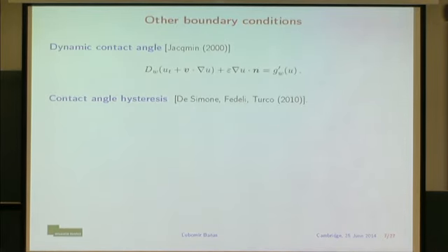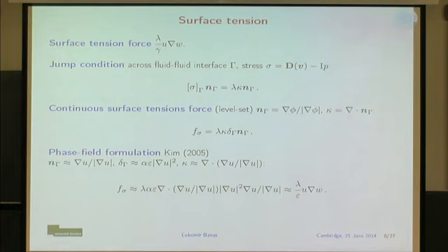Other boundary conditions are also possible. So this phase field framework allows for different modifications via the free energy approach. So for instance, we can take a dynamic contact angle, which has been proposed by Chuck Min, or one can also deal with contact angle hysteresis. Some work has been done by the people mentioned here in this area. So more complicated phenomena can also be incorporated in the model.